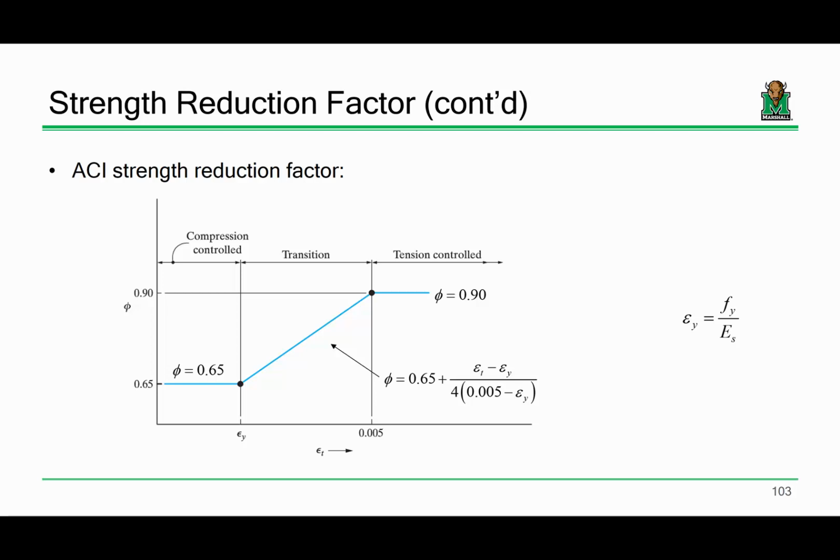In fact, in reinforced concrete design, if you really have an understanding of C equals T, compression equals tension, the more steel, the more reinforcement that you throw into the beam, the more you are demanding of the concrete. A lot of people think, well, here's my beam, I'm just going to throw a few extra pieces of rebar in there for good measure, make me feel all warm and fuzzy at night.